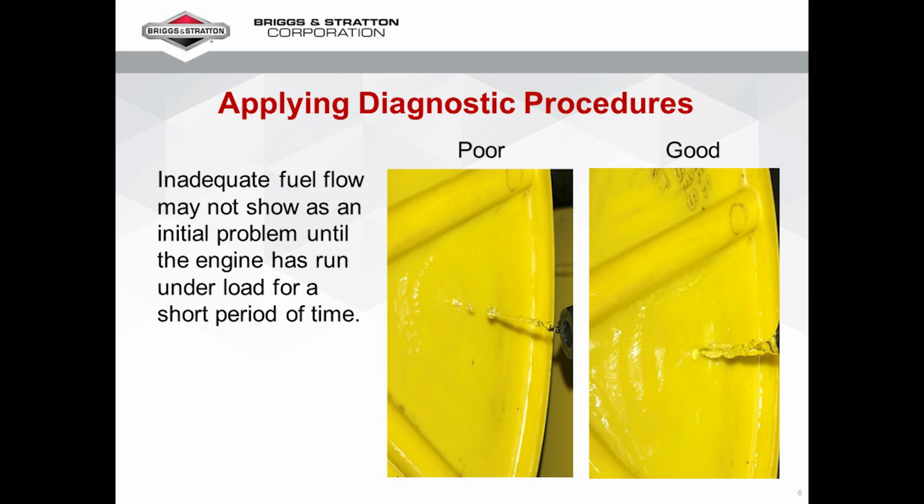If the fuel barely trickles out, this would indicate there is a restriction upstream. Either the fuel line itself is failing internally, there's a plugged fuel filter or screen in the tank, or improper tank venting could be at fault. Doing this test every time will save you the potential wasted effort and also allows you to verify that the fuel condition is well at the same time.